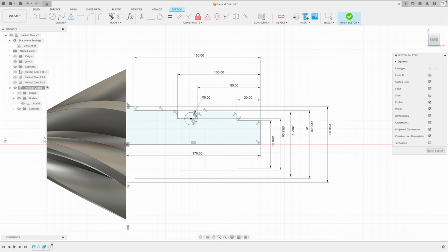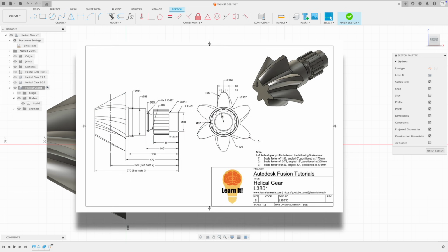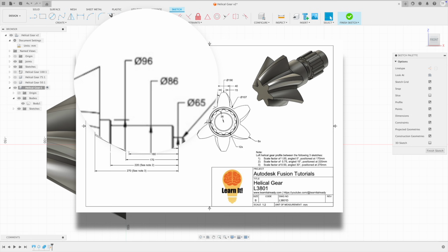So anyways, we've got all this. I'm just going to straighten out my dimensions a little bit more, make it look pretty. I also want to verify that I have all the dimensions on my drawing. Just so you know, my workflow that I used to do in the shop that I worked for is, as I was designing, I would highlight each dimension on my drawing, and then I'd go back and double check, and I would check off those highlighted dimensions.